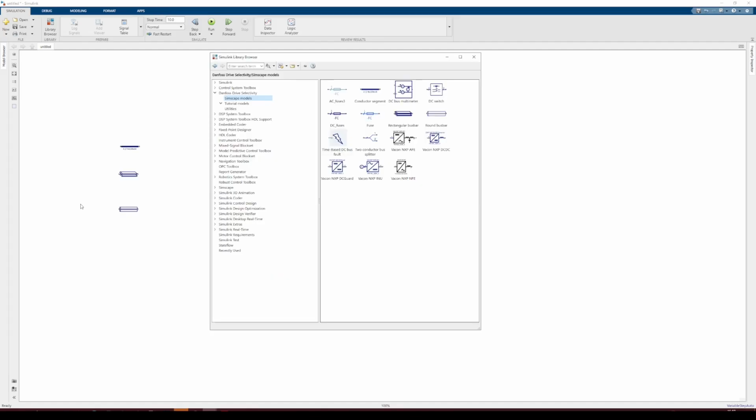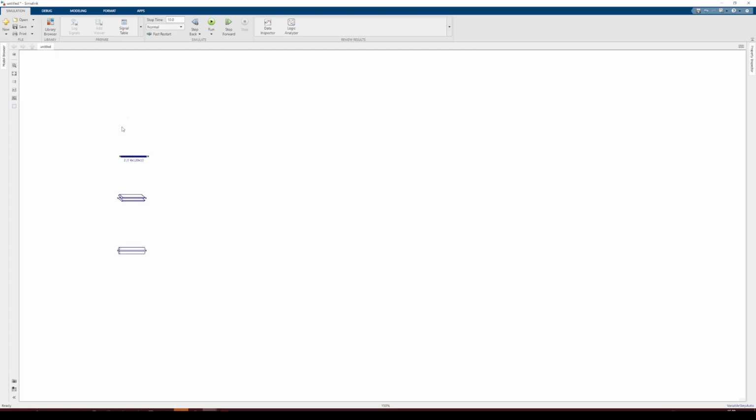An important detail in the system fault and fault current simulation is the impedances of the current carrying conductors. Namely, they are very important because the magnitude of the peak fault current, and also the current in the different nodes of the circuit, is dictated by the impedances between the sources and the point of the fault. In Danfoss's toolbox, we are delivering at the moment three types of conductor models, and these are shown in the picture here.